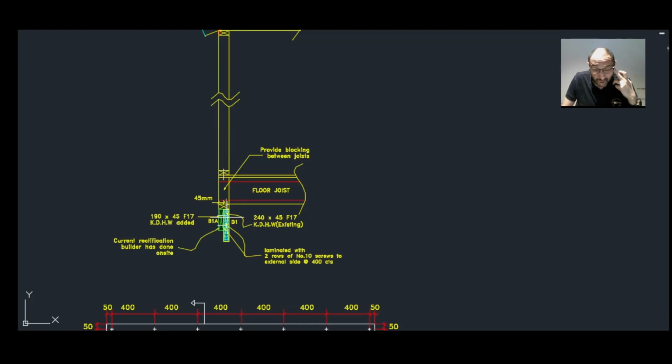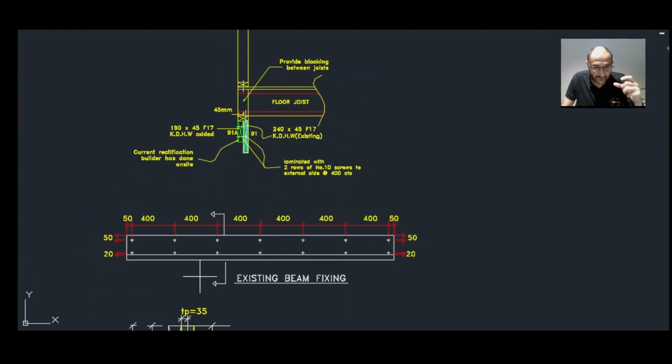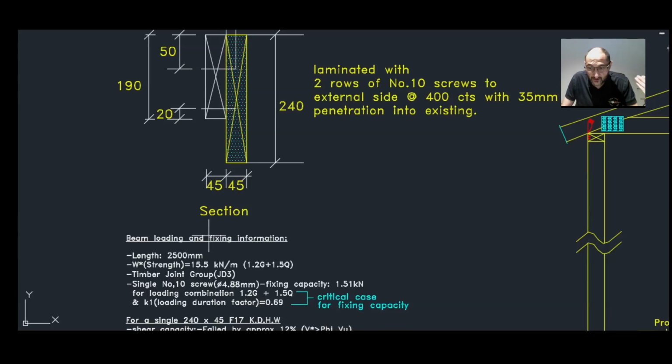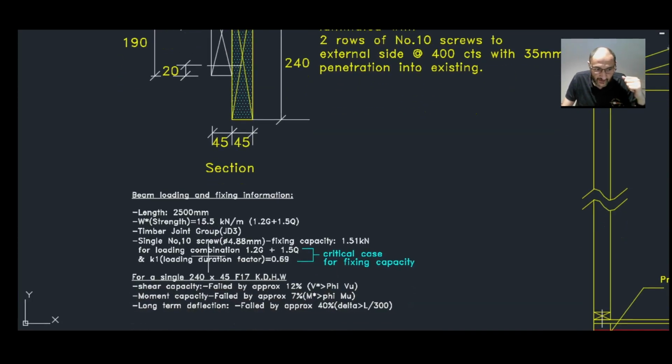where in the NCC, the National Construction Code, what does it say about the tolerance that has been allowed? There's also a guide to standard and tolerance handbook that you can refer to. You might be able to download it for free from the internet. So go back to that and see what it says about the tolerance of the overhang. Now, if you have gone through this whole checklist and everything is okay, then I cannot see why we can't use a standard nailing plate, with nominal fixings.